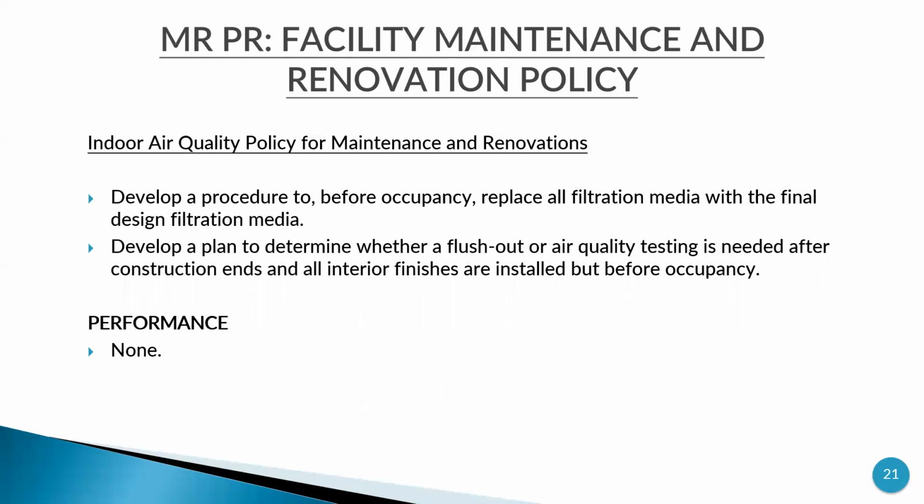Develop a procedure to, before occupancy, replace all filtration media with the final design filtration media. Develop a plan to determine whether a flush out or air quality testing is needed after construction ends and all interior finishes are installed, but before occupancy. This is one of the important points. So basically before occupancy, they should perform an air quality test.